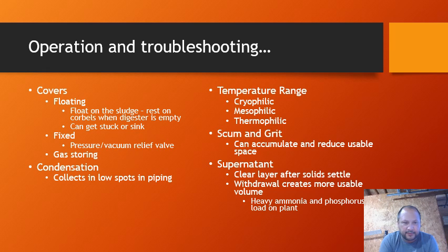The floating cover has a space between what I would call the roof of that digester lid and let's say the ceiling or the internal bottom part that you would see if you were actually inside the digester. There's a space in between called the annular space that's filled with air that allows that cover to float up and down on the sludge.